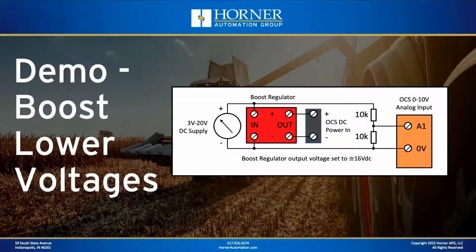All right, so this is the next demonstration I'm going to show you, and that is using a boost regulator in between the supply voltage and the OCS to boost the voltage to the point where we, at least a lot of the time, don't have any engine cranking resets, and we also should almost never have the issue with the OCS doing the cycling because of battery drain. So let's head back to the bench. There's really nothing to talk about from a software standpoint. This is purely an electrical solution I'm talking about here.